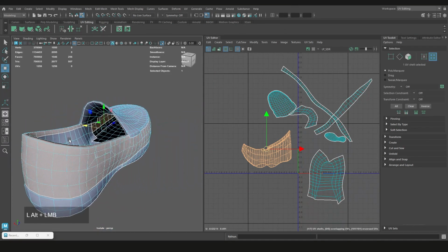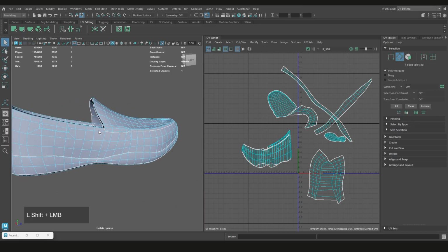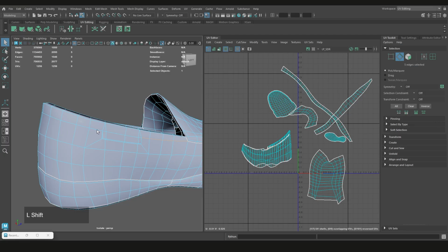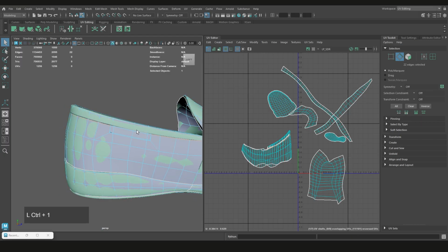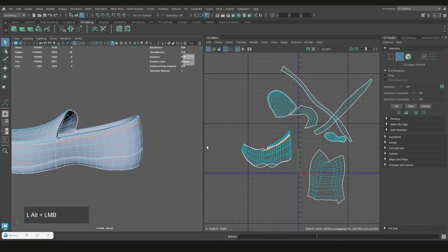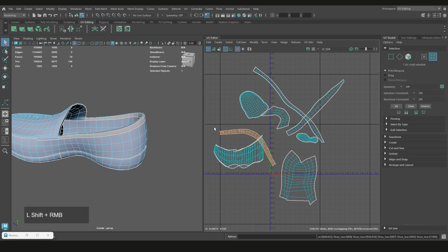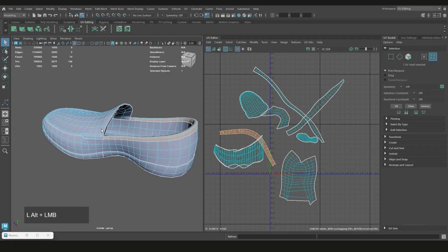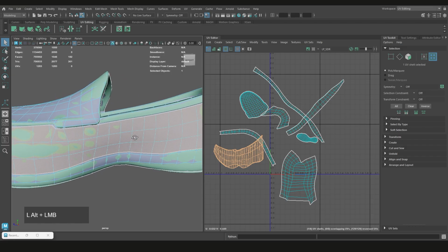Here I'm thinking maybe we do this separately as well. So I'm going to go to the edge. So this piece here is actually separated, so I'm going to shift double click on there, and from there to there. Yeah, so this piece here can probably be separate. Actually, you know what? I'm going to undo that. Press Ctrl 1 to see where that is. Oh, okay. Yeah, so from here to here, this here can be cut as well. Okay, there we go. So UV shell, that piece there will be its own piece. So I'm going to say unfold and unfold, right? And this piece here is one. So I'm going to press Ctrl 1 so I can see where I can put these cuts.